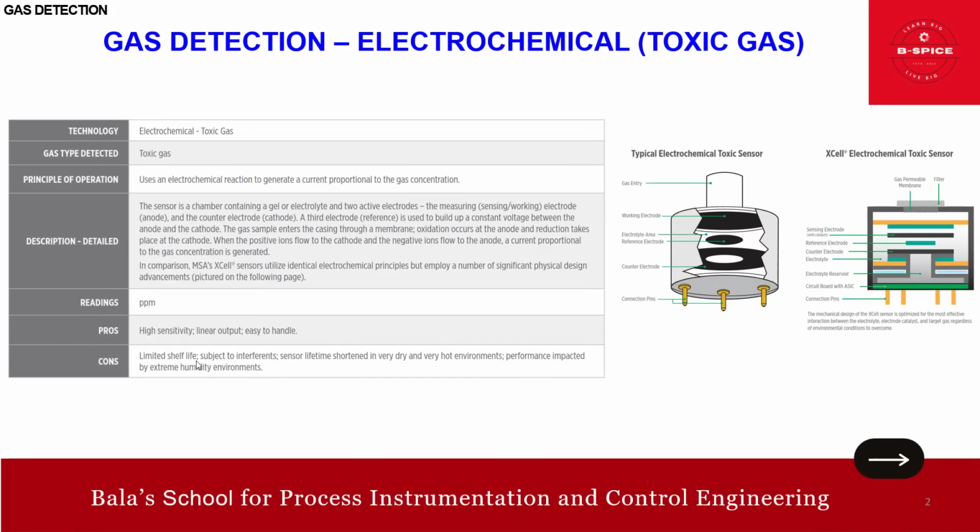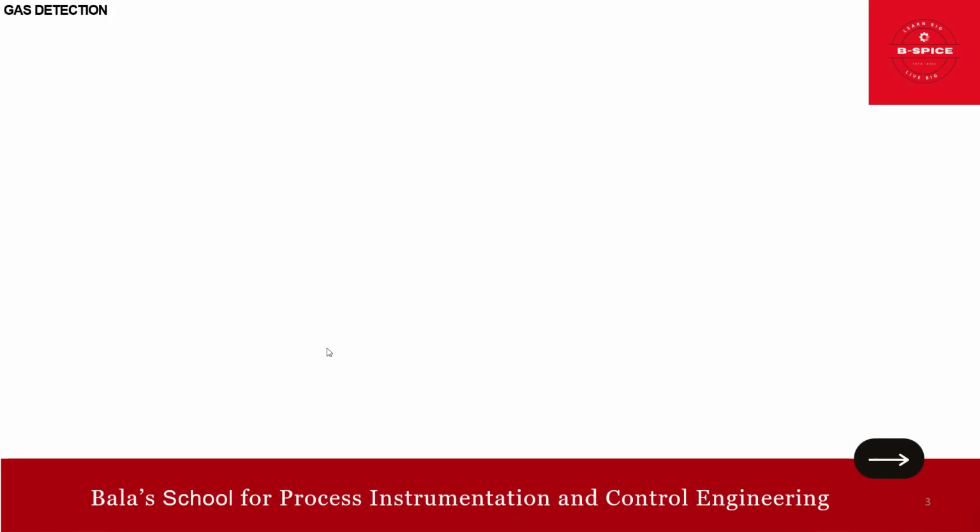Limited shelf life. You can't keep this for a long time, so we need to verify the shelf life when we order. It's also subject to interference, and sensor lifetime shortens in very dry and very hot environments. The performance is also impacted by extremely humid environments. So we need to take care of all these, friends. That's all about the electrochemical toxic gas.